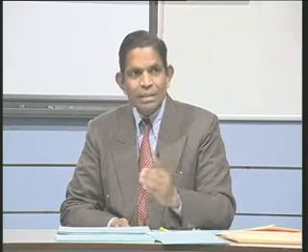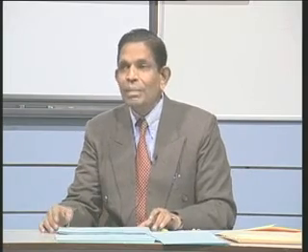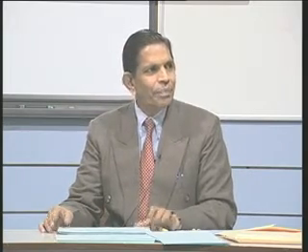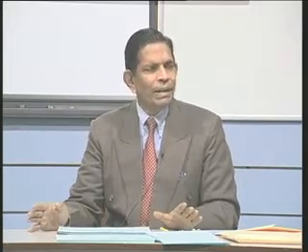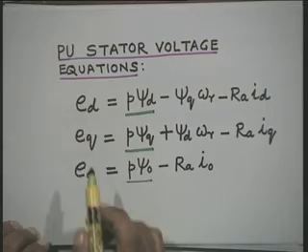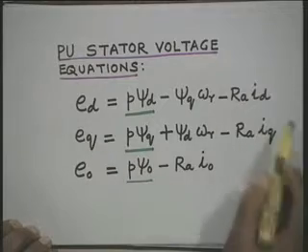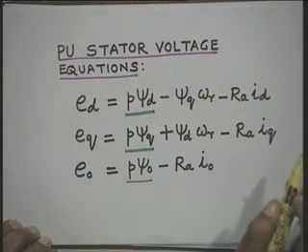Once you read this, you will come to a very important inference that yes, for stability studies one can comfortably neglect the stator circuit transients. And the moment you neglect the stator circuit transients, we get a very big simplification: the stator circuit voltage equations become algebraic equations.